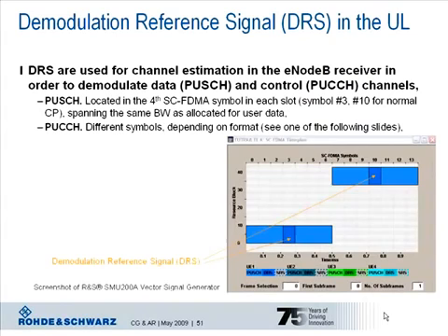To ensure proper demodulation, demodulation reference signals are used in the uplink. In contrast to the reference signals used in the downlink, the demodulation reference signals are not transmitted on specific resource elements. Instead, the demodulation reference signal is transmitted over the entire allocated bandwidth and occupies a specific single carrier FDMA symbol.